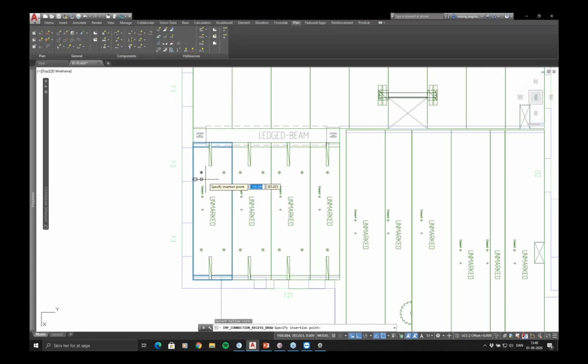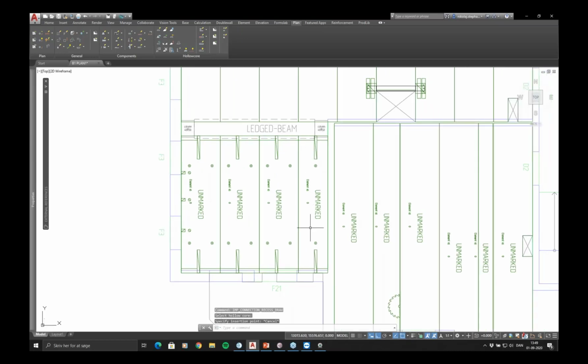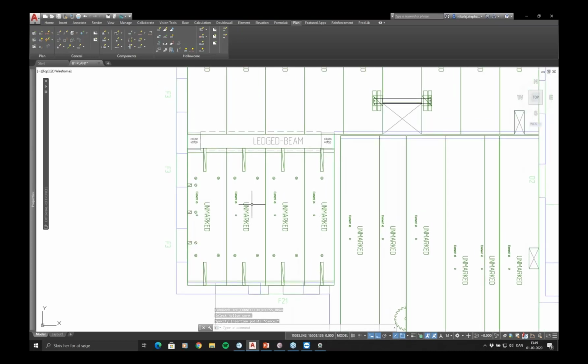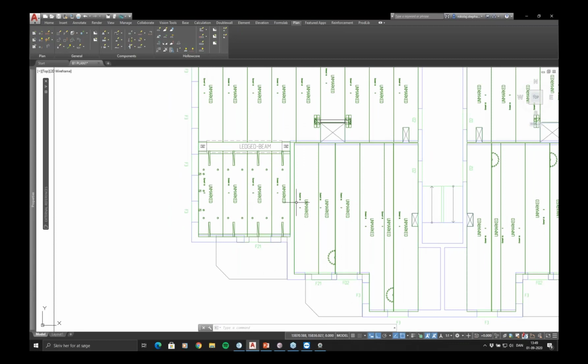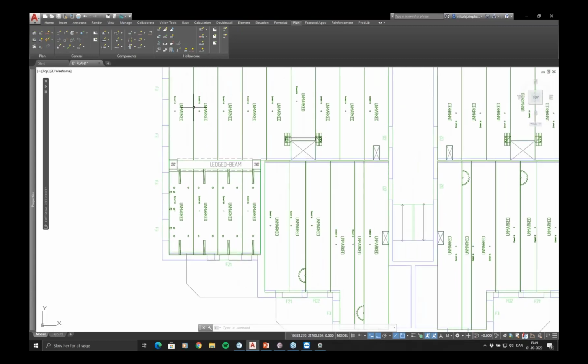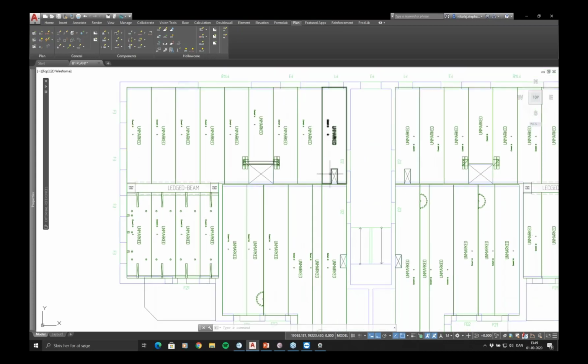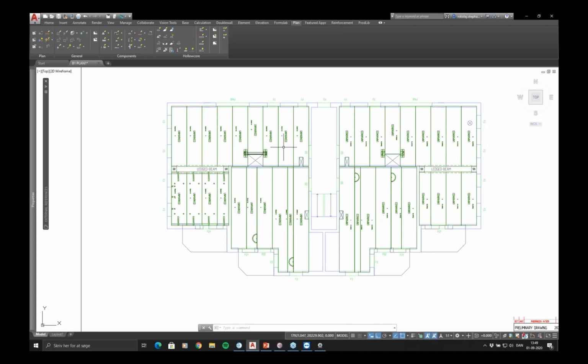Depending on what we need, we can just add it, or actually we can standardize it as well to have it add these things automatically. And this one we cut here, so there's probably not that much point in putting them in, of course. So now we have some elements up here and some more detailed ones down here. It completely depends on the type of Hollowcore that you do in your company. Some of you don't even put recess in the Hollowcores. Some put both round recess and rectangular recess in. So there's a different mix of what each of you does.